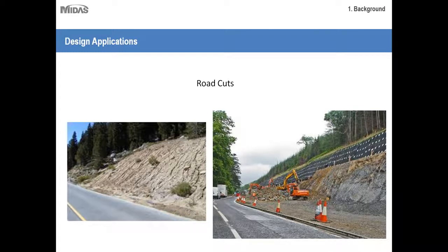So that's just another thing that you have to keep in mind as an engineer, that depending on the project conditions you have, you might have to create certain fail-safes just in case the slope does fail. Because the slope is very high and very steep, the engineers felt that the design required several fail-safes or design precautions just in case the slope did fail. Whereas with maybe more stable materials, you don't really have to worry about those precautions. So once again, road cuts would be just another example of design applications for slopes. I'm sure you've seen them around.